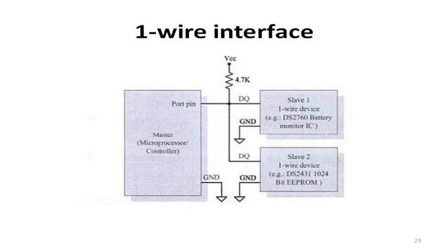So beside electrically erasable programmable ROM device, the strong pull-up also powers one wire temperature sensor and special functions such as SHA1 engine, which is found in secure one wire device. Temperature logger, the I button, use SRAM technology and therefore do not have any special external power requirement.